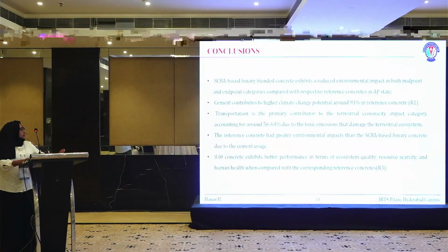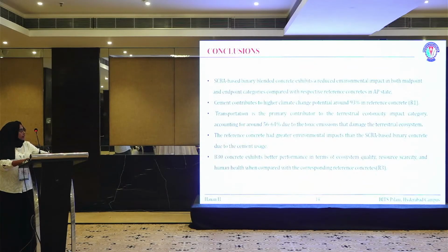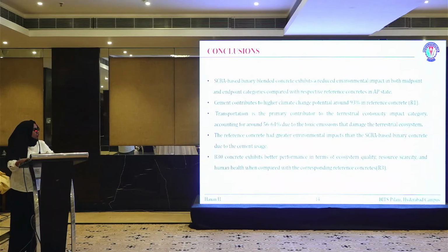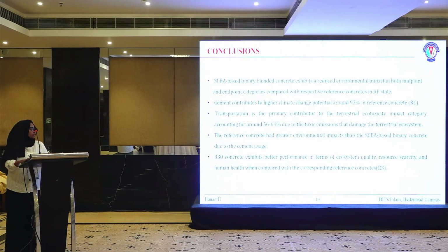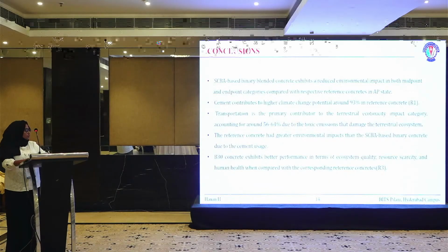So moving to the conclusions, SCBA based binary blended concrete exhibits a reduced environmental impact in both the endpoint and midpoint impact categories with respect to the respective reference concrete. Cement contributes to a higher climate change potential, around 93% in the reference concrete, and transportation is the primary contributor in the TET impact category, and the reference concrete had a greater environmental impact than the SCBA based.